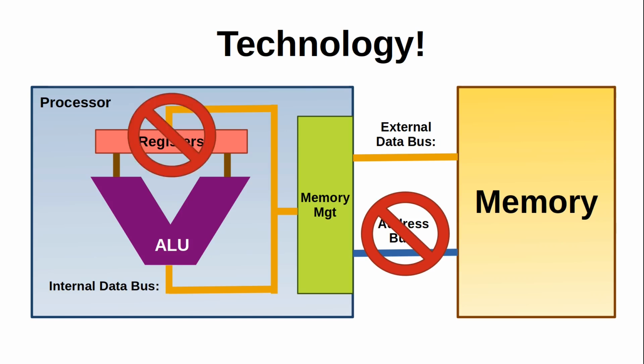And it's also not the registers, because the Z80 technically has 16-bit registers, and even the 6502's program counter is a 16-bit register. A lot of other 8-bit computers have 16-bit registers, but they're not dealing with data in 16 bits in any other part. The external and internal data buses on all of those 8-bit processors are just 8 bits.